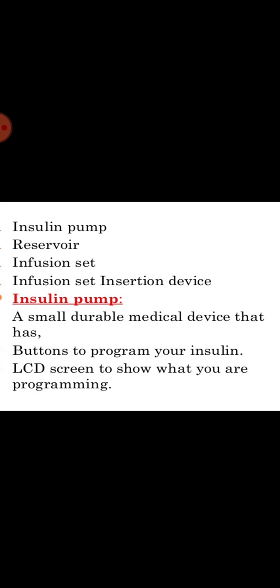So, in order to fulfill these requirements, a stepper motor driven roller pump with swing-out counter jaws is employed as the pump. The device is of the demand type on a preset basal rate. A supplementary dose of insulin of selectable sizes is called up by the patient at meal times. The supplementary dose is administered as a rectangular rate profile with variable time or amplitude.